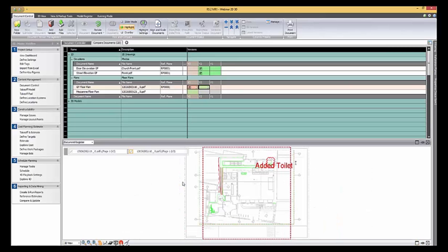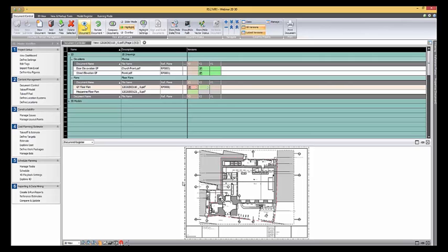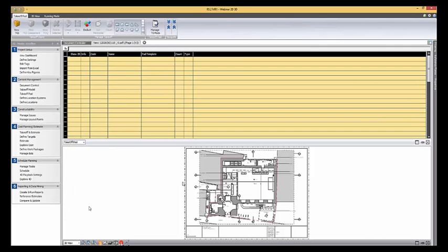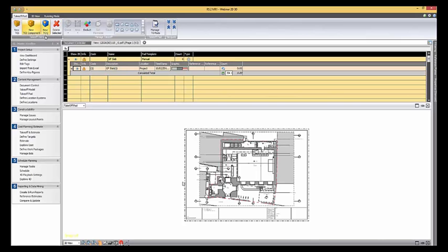The next thing we're going to do is a manual takeoff. So we're going to load up the latest revision of the drawing first. And then I'm going to switch to my takeoff pad, which is where I do all of the takeoff. I've decided to start by measuring that ground floor slab. So first thing I want to do is create an item, ground floor slab. And then I'm going to use one of my pad templates that I've set up.